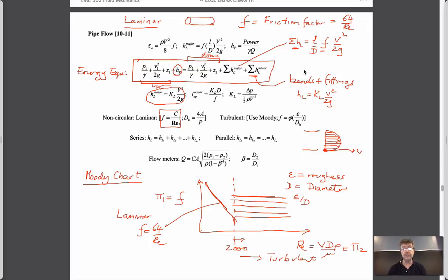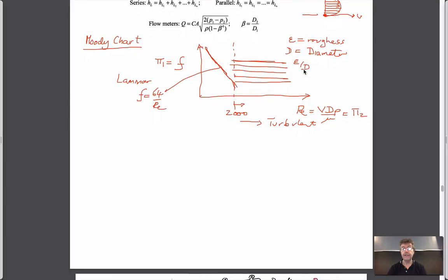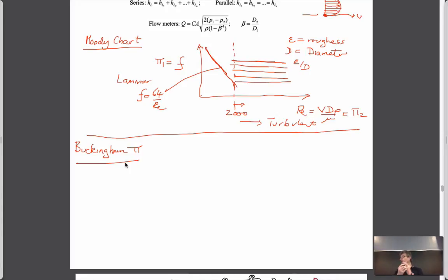I suppose what we could also do is we could go back to our discussion of Buckingham pi and figure out exactly how we would end up getting this particular chart. And so let's kind of do that. So let's go back to Buckingham pi. So we made these three comments. We have to have dimensional similitude, has to look the same, exactly scaled model. If it's then kinematically similar, we have a chance of being able to do something about it through the Reynolds number. And then we can measure some other parameter, such as the Euler number, that will describe our system.